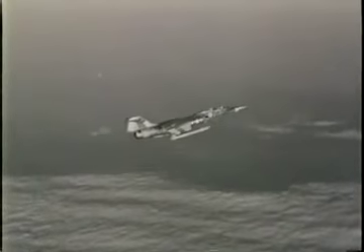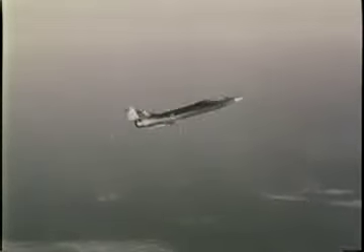Without any supervision, a supersonic flow tends to slow down abruptly through a strong shock wave with a large loss in stagnation pressure. The deceleration in a normal shock wave like this one in a large wind tunnel is thousands of millions of gravities, and the word shock is certainly appropriate. There are very large gradients of velocity and temperature inside such a shock wave, and large losses in stagnation pressure due to viscous dissipation and heat conduction.